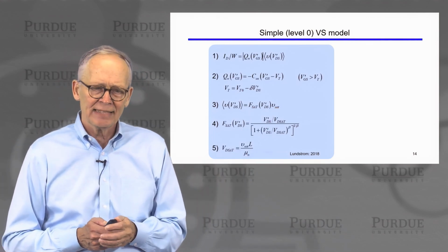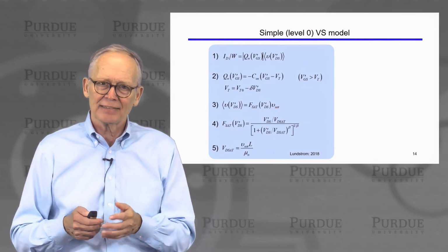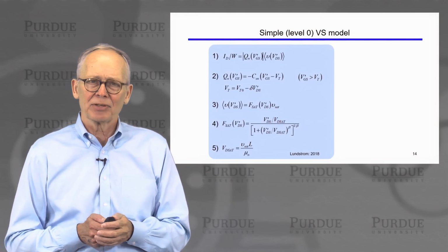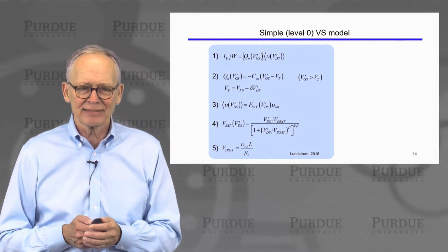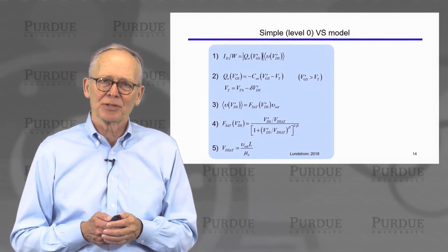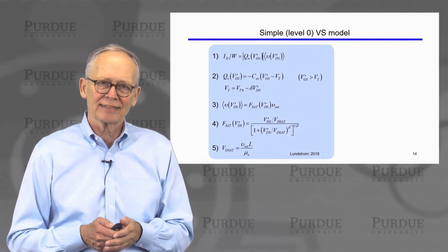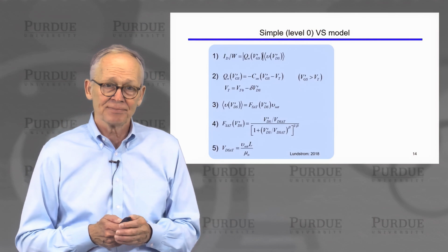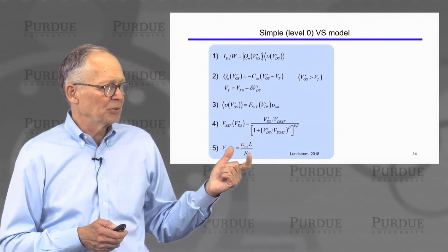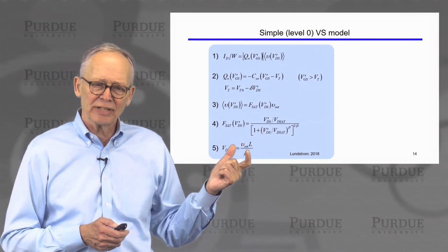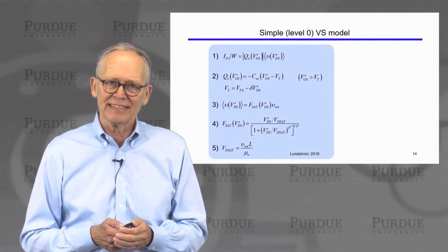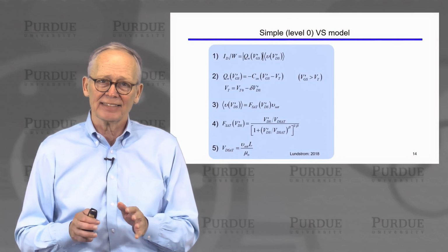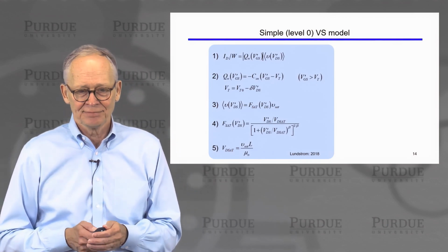The average velocity is this function fsat times the saturation velocity. And that function is semi-empirical. It's based on some physical reasoning, but it includes an empirical parameter, and it smoothly connects the velocity in the linear regime to the velocity in the saturation regime. And there is a transition between the two that occurs smoothly around the voltage we call VDsat, which is significantly less than VG minus VT in the square law device.